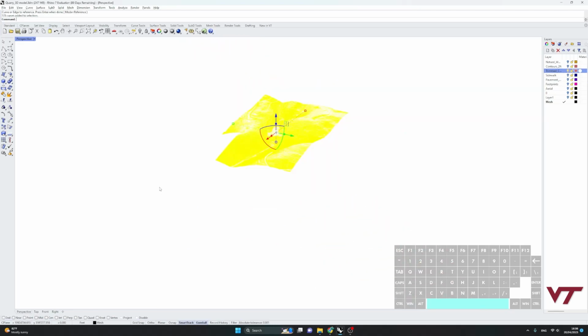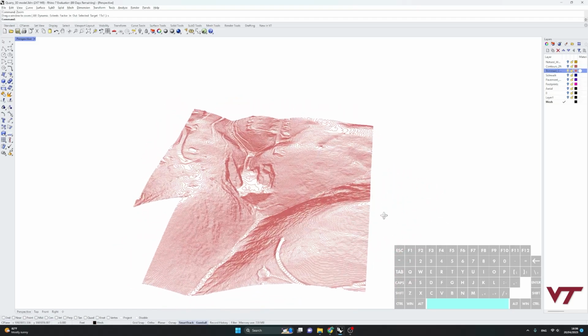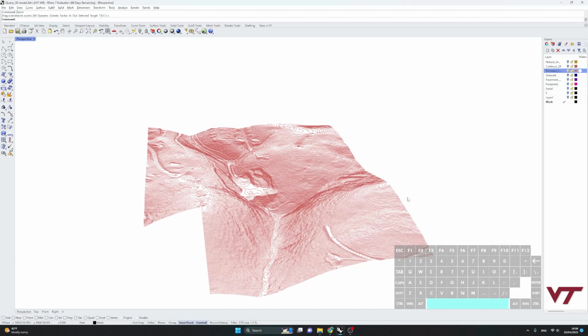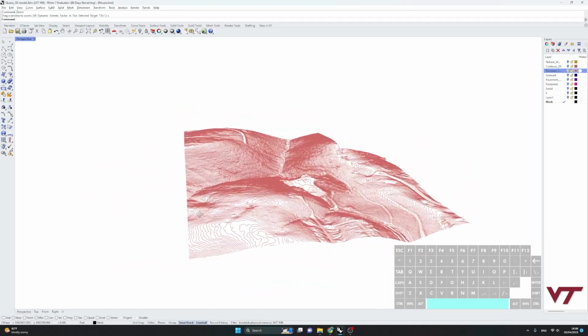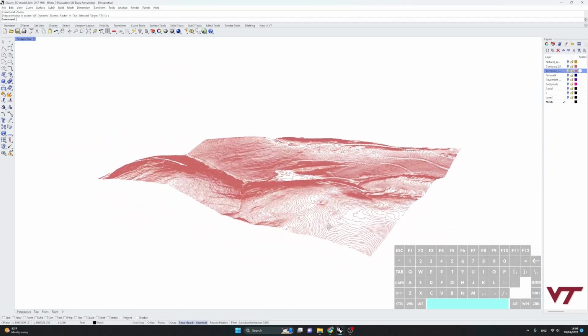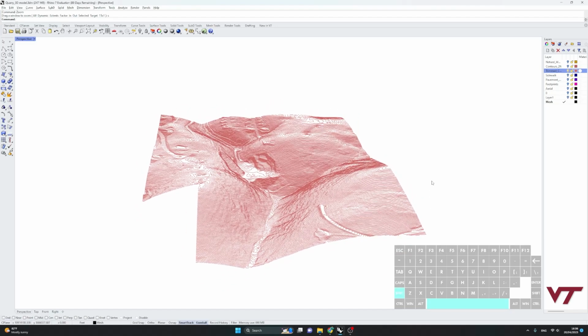If we scoot over here and zoom in a little bit, this is the contour data, which most of you are going to be fairly familiar with. That's an abstraction of topography elevations. Each of these contour lines represents a 2-foot change in height from each other. By and large, most times you get contour data, it's going to come in 3D like this. Each line is elevated 2 feet up from its neighbour, or down, depending on what direction the slope's going. But it doesn't always come in with that.